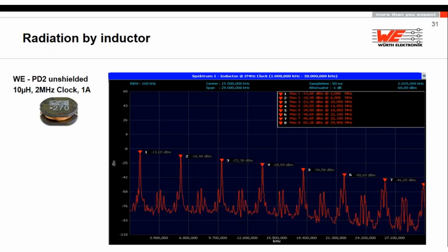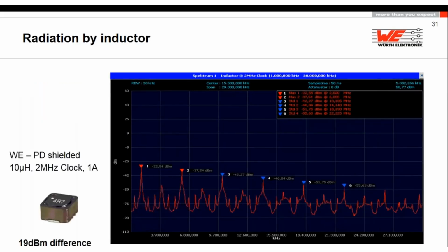If you look just at the conducted emission, 150 kilohertz to 30 megahertz, at these peaks generated by a very simple DC-DC converter, and you just take a soldering iron, don't change anything on the setup, not move even one piece of wire on the desk, desolder the inductance from the unshielded version and solder the same inductance value on the same pad, a 10 microhenry shielded version.